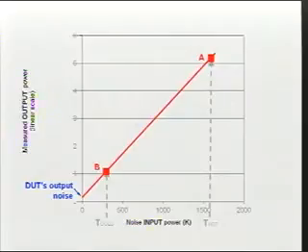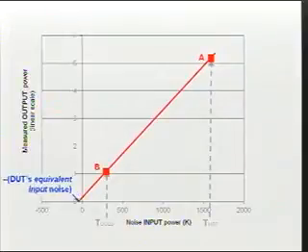In order to get at the noise temperature of the DUT itself, we extrapolate that even further. Now, don't worry about the negative temperature axis there because, okay, there's a minus sign there, there's a minus sign there, no laws of physics are being violated.